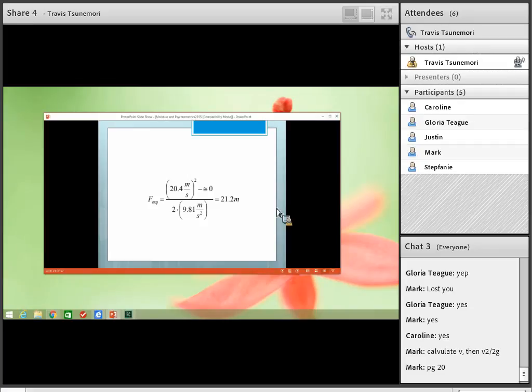So now notice the relative magnitude of the expansion pressure drop versus the pipe. So the pipe was 3.2, and now the expansion is 21. So it has a bigger effect than the pipe did. Okay, so now we're on to the floor. And if we use equation 2.39, we need to know the velocity, the percent opening, and the void fraction. And I think those were all given.